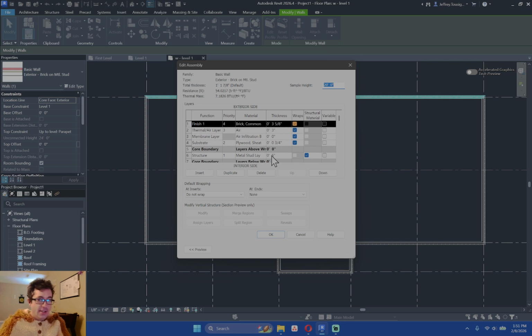The disadvantage of this, which would come from centerline anyway as well, is if you change the stud size, it will remove or add to square footage inside the building. So I like one thing to at least be consistent. The footprint of the building's consistent, and then if you have to adjust the studs, you're taking from your interior square foot, which could be good or bad depending on how far in the project you are.